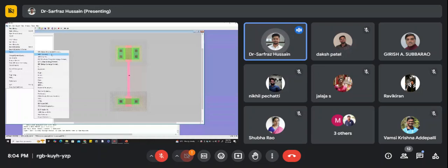And when you click on this one, GDS2 stream, all those things will be saved there, basically a text file will be there which will contain all the information of your layout, like what is the minimum size, minimum distance you have taken, what is the distance between two metal layers, what is the distance between the polysilicon and the metal. So all those informations will be there in the GDS file, and based on this GDS file only your particular fabrication will be done. So I suppose this is just a brief of what actually we can do.